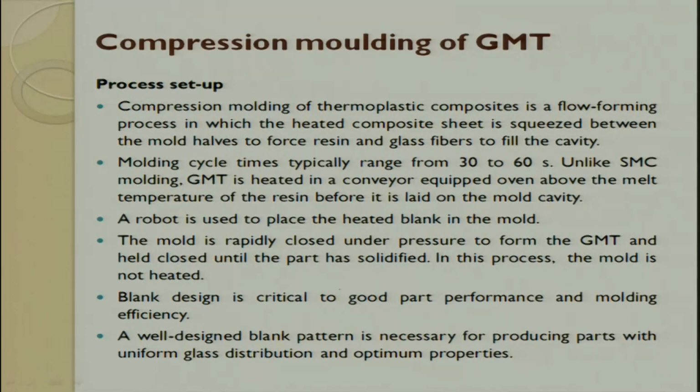So what are the processing steps? The first step is that compression molding of thermoplastic is a flow forming process in which heat is applied to the composite sheet and it is squeezed between the molds. Then it is maintained for 30 to 60 seconds.